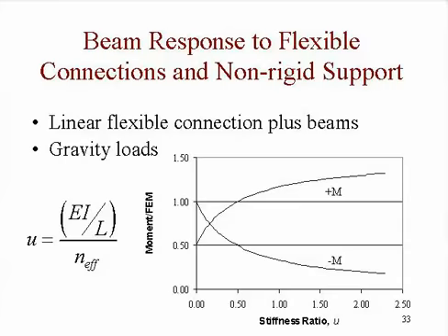So again, we come back to the same behavior for the beam. All right? So whether that central section, which was the uniformly loaded beam, is just attached to 2 linear springs, or it's attached to 2 linear springs which are then attached to 2 beams or to 2 columns or to a whole structure. And even if the connection is not linear, but we know the secant stiffness, right, the straight line that connects 0 to the point of equilibrium, we're back to knowing the exact behavior of that beam.